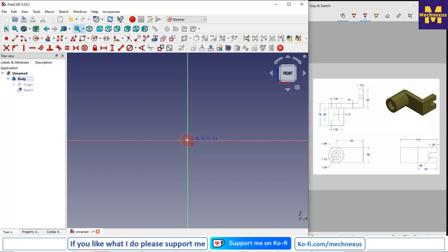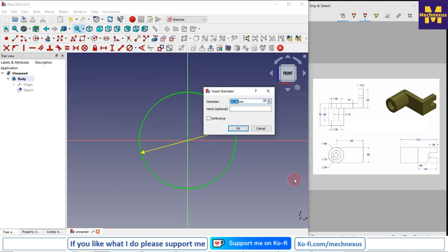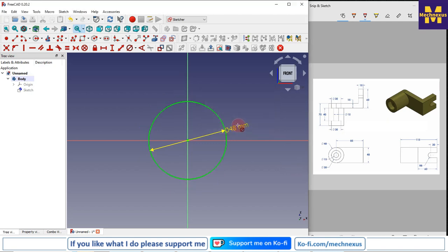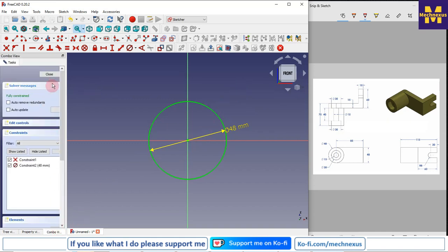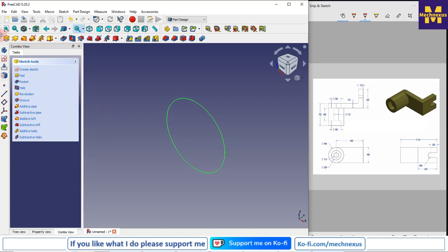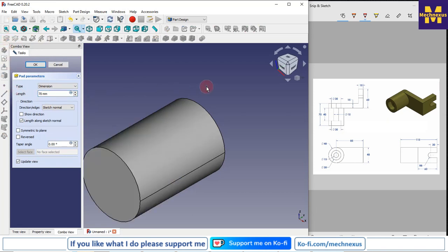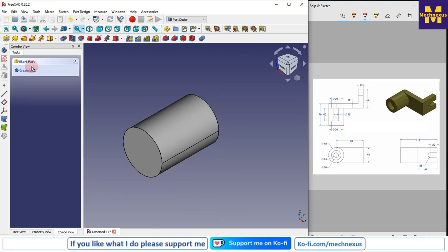So first we will make the circle for the boss, and then we will constrain it with a diameter which is 48, and the length of this boss is 70. So I will come out of the sketch, and then I will create the pad and give my dimension 70, and I will say OK.